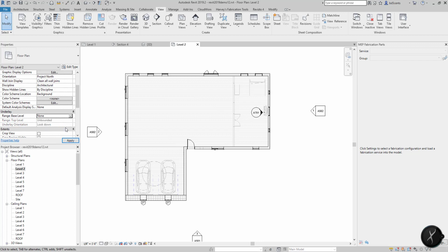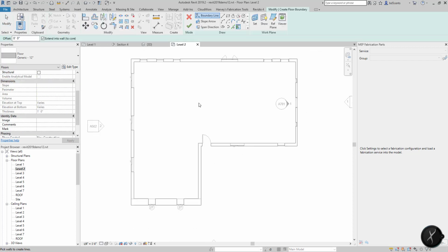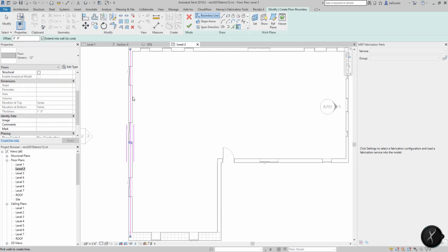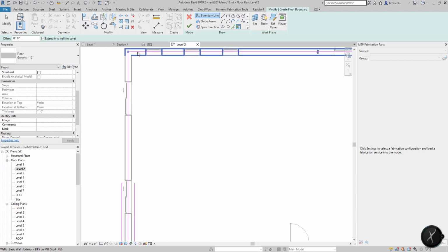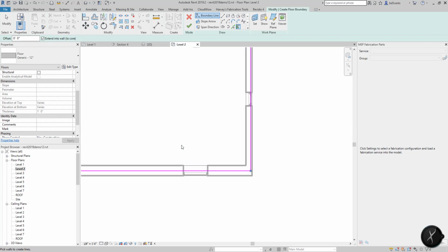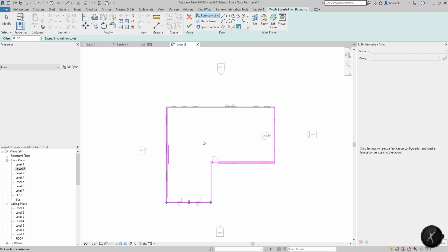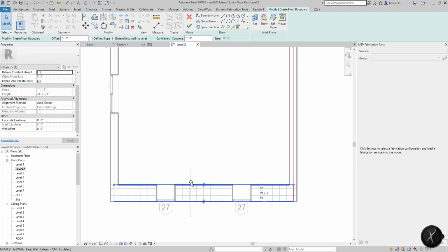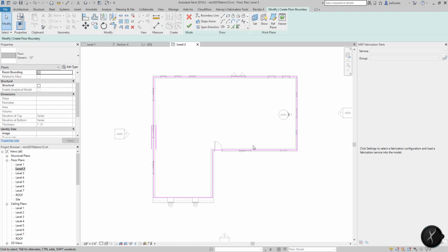We're going to turn it back to none for now, and we're going to just draw a floor in place, architectural, and we're going to select walls. Right now, notice that it's defaulting to that wall center line. That's fine for now. That's selected correctly to that stud, so we're going to just stick with that for now. Notice that everything's drawn in there. This one we'll go ahead and just put on the back just because I don't want to see it on the exterior. So that's drawn.